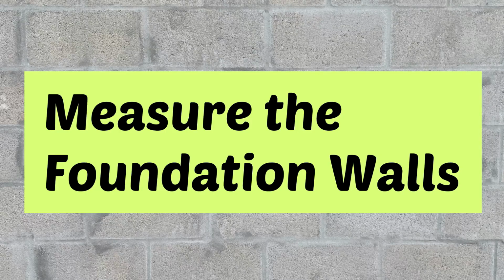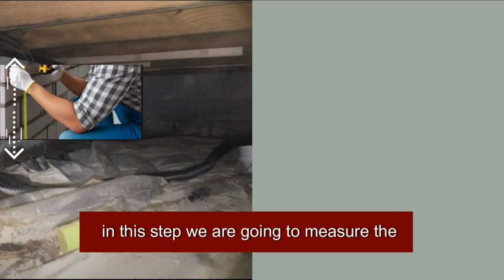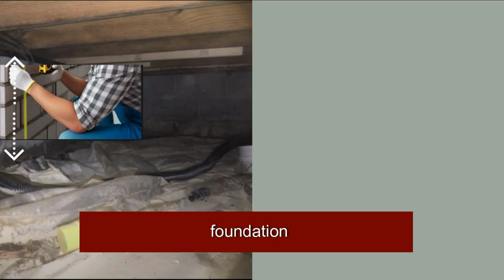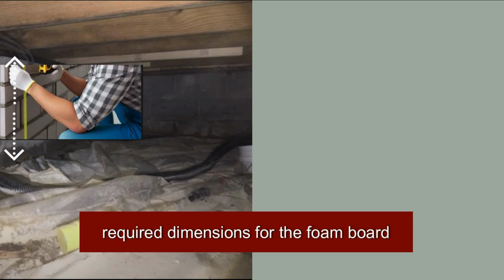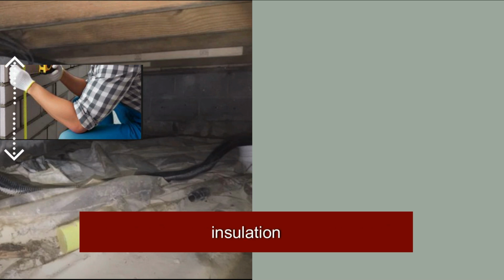Measuring the foundation walls. In this step, we are going to measure the foundation walls vertically and horizontally. This will give us the required dimensions for the foam board insulation.